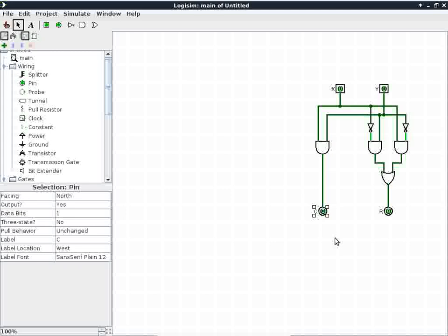All right, so I'm going to test this. Now it is actually being tested already. If you notice what is inside the bubble, it's kind of hard to see, but there's a 0 here, a 0 here, a 0 here, and a 0 here. In other words, the circuit is actually being simulated as we designed the circuit. So this is basically 0 plus 0 has a result of 0 and no carry. Makes sense, right? So we want to test all of the other cases.